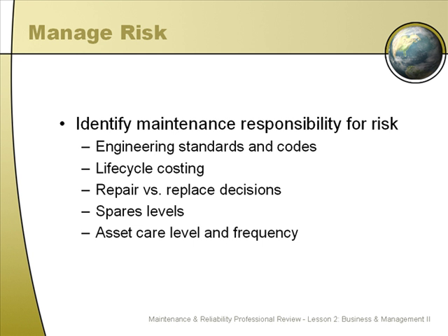Second, life cycle costing. Life cycle costing is a simple thing. It's really the calculation of the total cost of a piece of machinery from its installation until the day that it's disposed of, including the costs to purchase it and dispose of it at the end. It's quite interesting that many times the initial purchase price is not the controlling factor in the cost of the life cycle of a machine. So it's important that maintenance, engineering, and operations work together to do a good job on life cycle costing so they purchase the right machines.